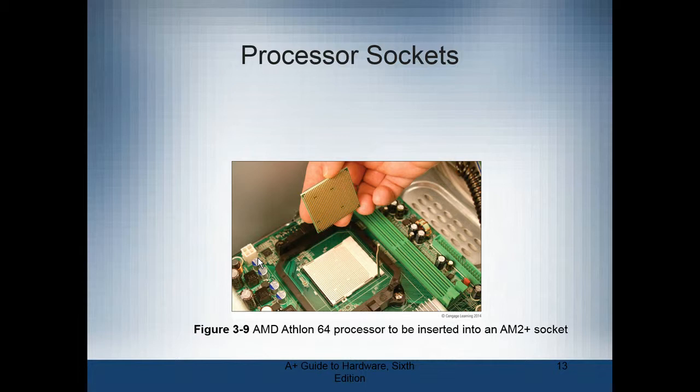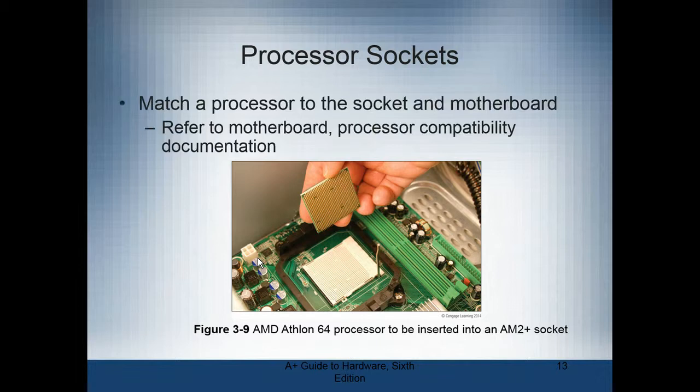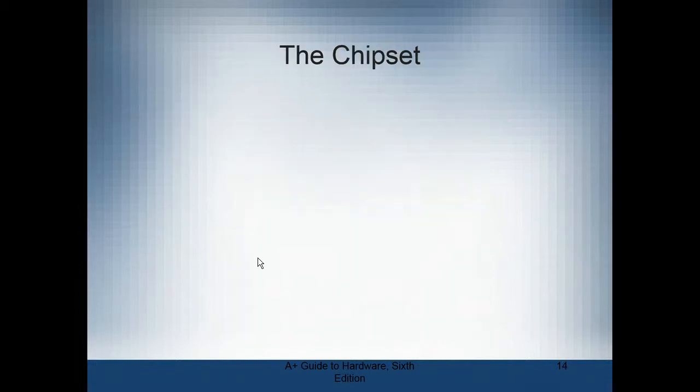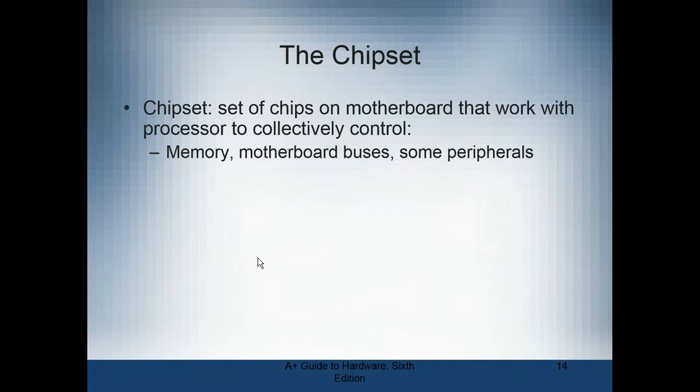They're getting ready to insert this thing. The lever here is the zero insertion force lever: up, drop it in. If it doesn't drop in cleanly, it's not aligned. You should be able to just drop it in and it will go down flat, and then you use the lever to lock the processor in place. And obviously you have to match the motherboard and the socket.